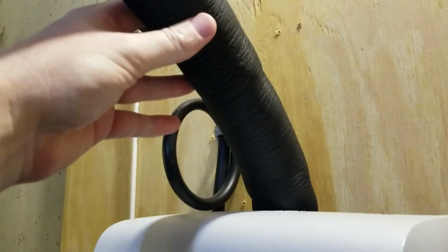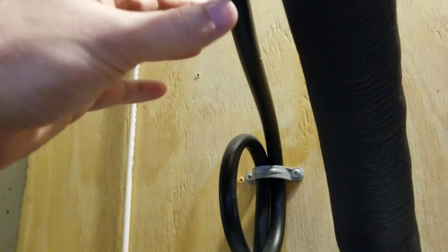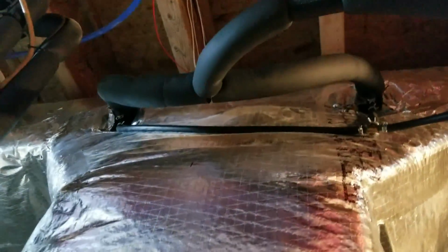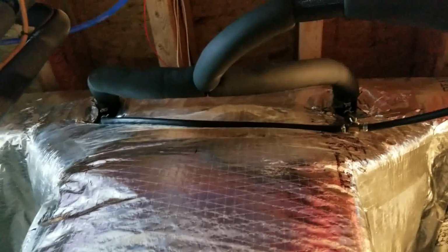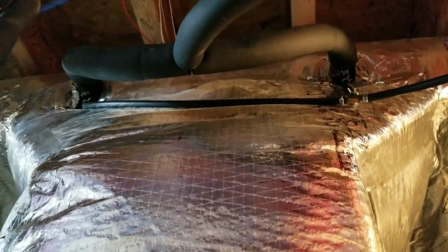So up here at the top, you'll see this is a rubber steam line with an insulator on the outside of it. This is a drain line for steam that condenses in the steam injector up there for it to drain back down. If you follow this up, it's probably hard to see on here, but this thing splits with a T into two. Because of how this ductwork is designed, I have two steam injectors instead of one, one on either side of the air handler there.